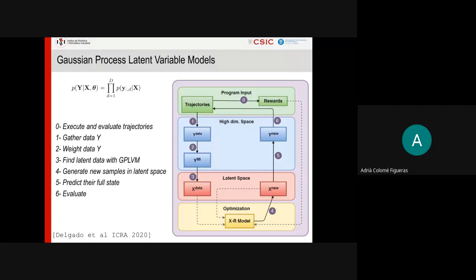We did the sampling and exploration there, so we could also do Bayesian optimization in that latent space, which was 2-3 dimensional instead of, let's say, 100 dimensional, find the optimum there and then project upwards. This helps a lot with sample efficiency, because, as I was saying, the number of samples that we execute on the robot is something critical for learning robot motion.